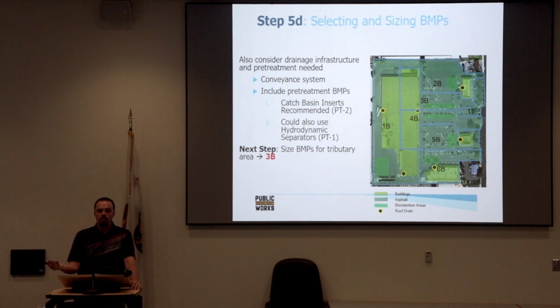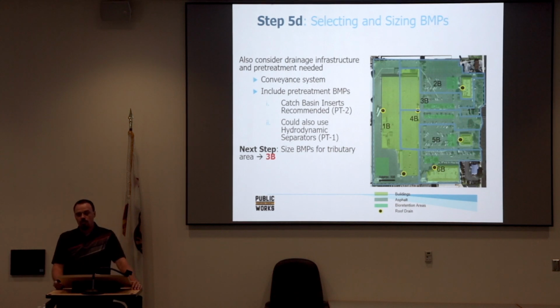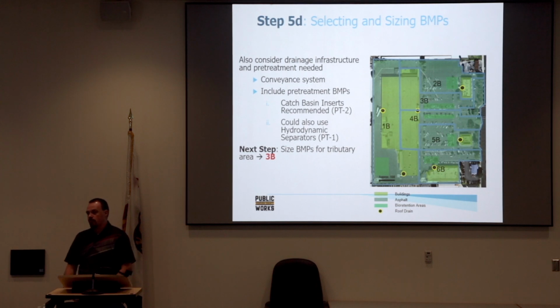Generally, for instance, permeable pavements. How do you do pre-treatment for a permeable pavement? You can't do it. The water goes through the pervious pavement and starts infiltrating. So you don't have pre-treatment removing the sediment, which is the main problem for the O&M portion of it. So there are some aspects of it that aren't realistic, but for the most part, they should be doing pre-treatment because sediment is the main concern. With most pollutants, whether it's pesticides, oils and greases, or metals, they attach to the sediment. So if you can control the sediment, you can control about 75% of your pollutants in many cases.